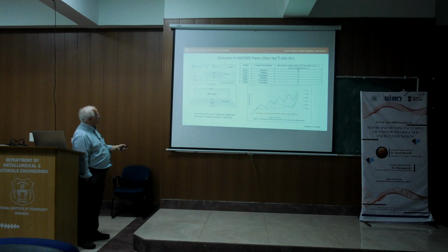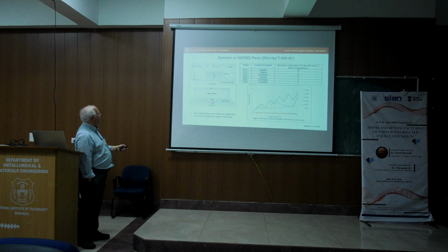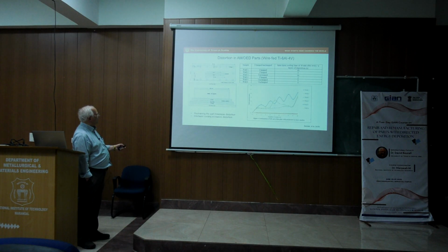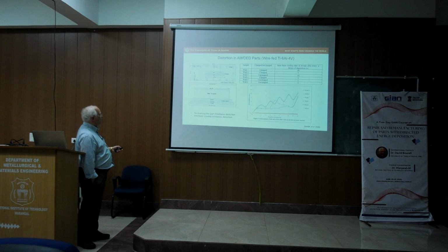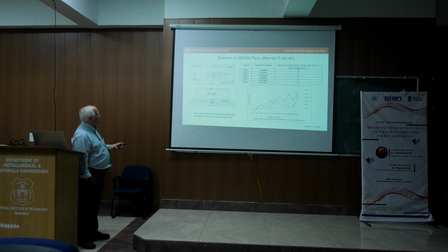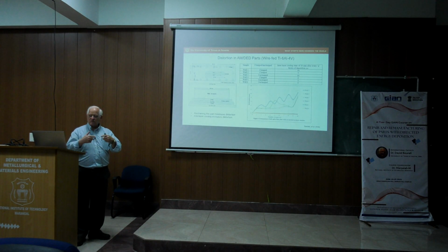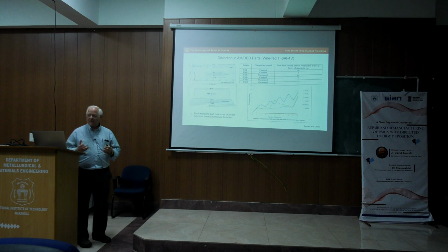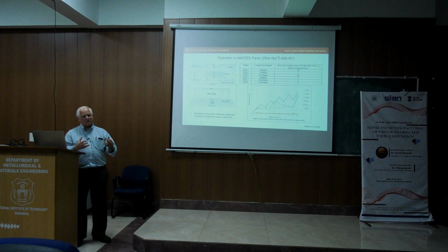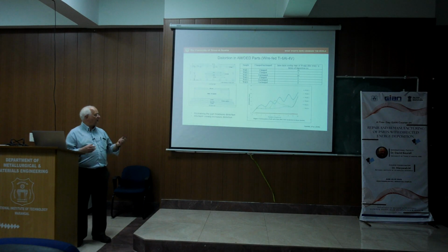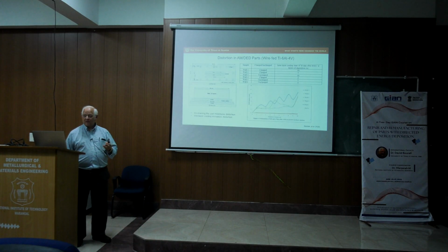this is a side view. Basically, they have various plates and some washers. They have the build plate here, and then they built a 10-layer wall, 200 millimeters this way. I'm not sure about the vertical dimension, but it shows what it is. Basically, they clamp the substrate down to prevent the residual stress from distorting it. And what they found is that by doing so, it resulted in less distortion in the final part.